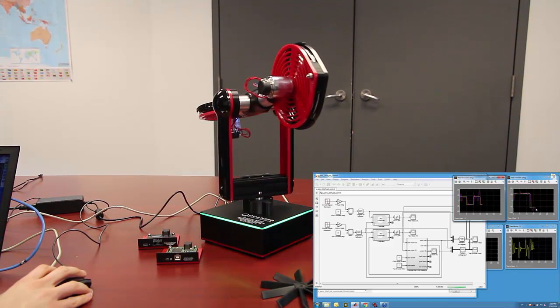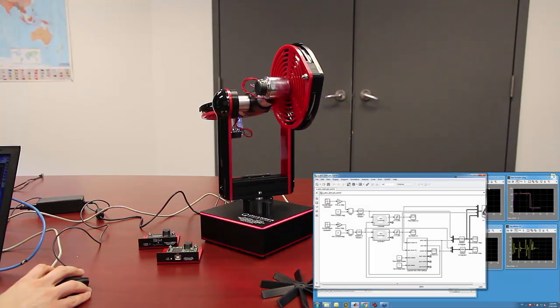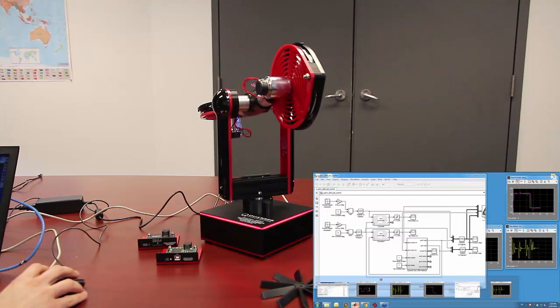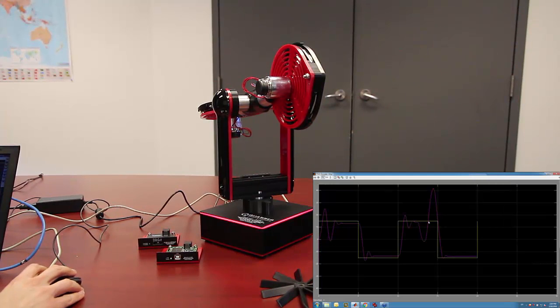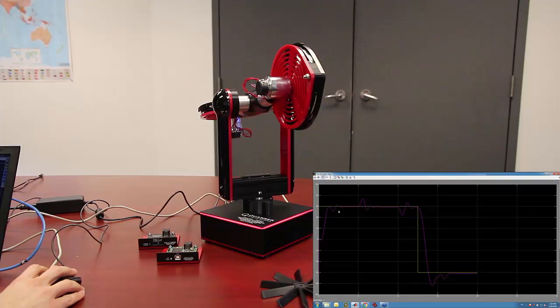Note that when it's changing in the yaw, which is a really big movement, I'm just going to stop this for a minute, then you'll see that in the pitch, you get a huge overshoot here, right? This represents the coupling. When the yaw moves, you get this huge motion in the pitch, and you should be able to see it on the screen. So here's the yaw encoder. When the pitch moves, you get these little perturbations, if you will, along the yaw, right? So the controller has to compensate for this.